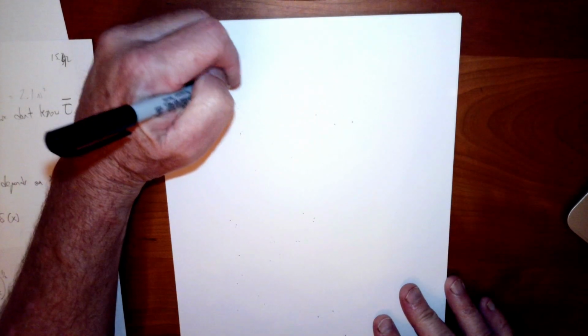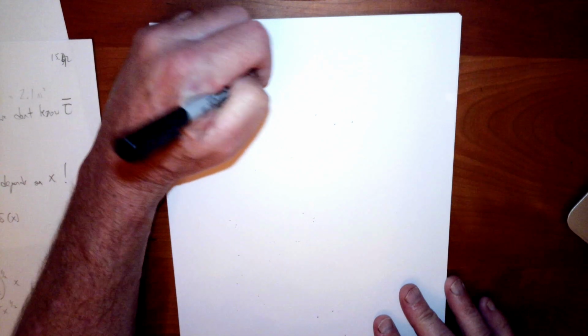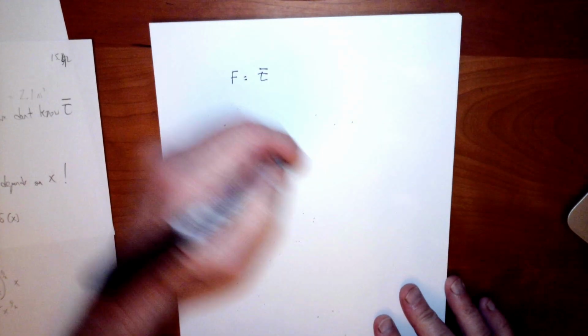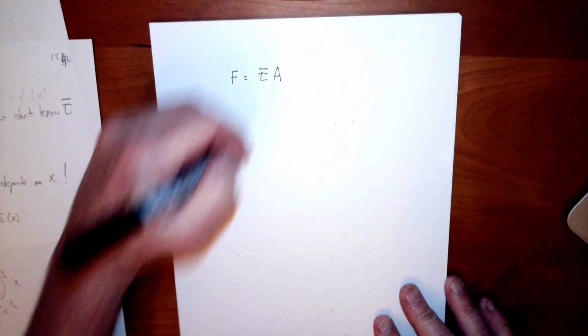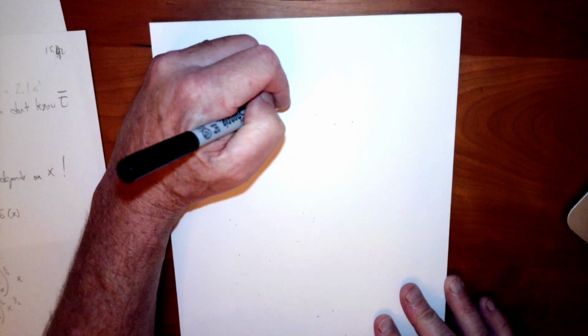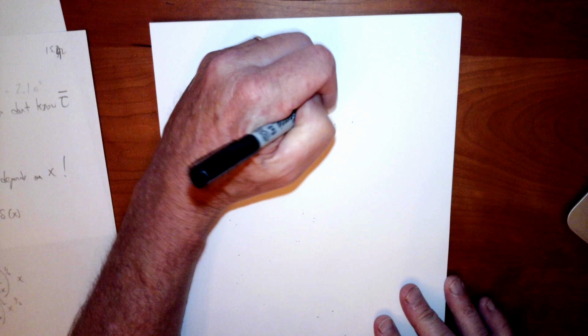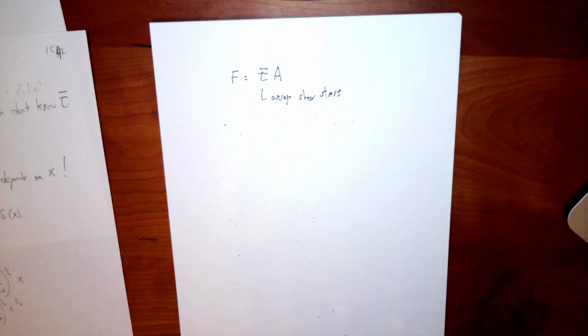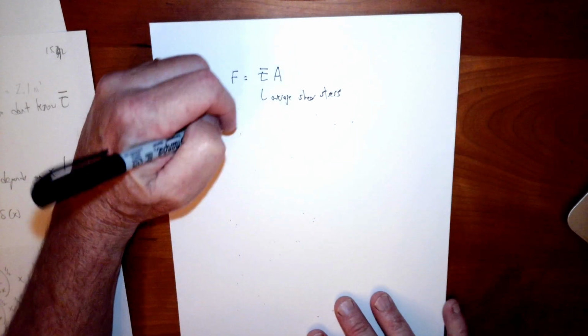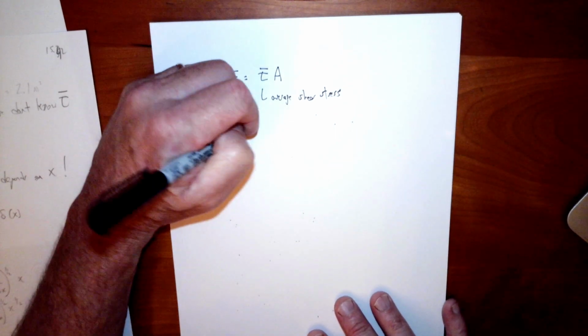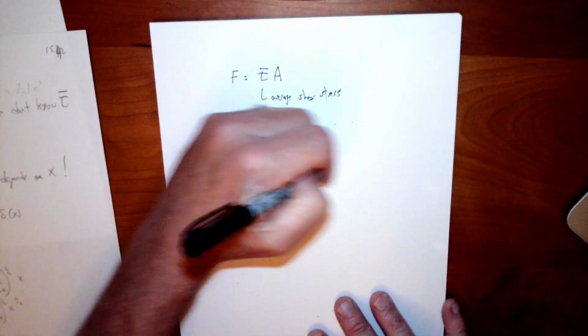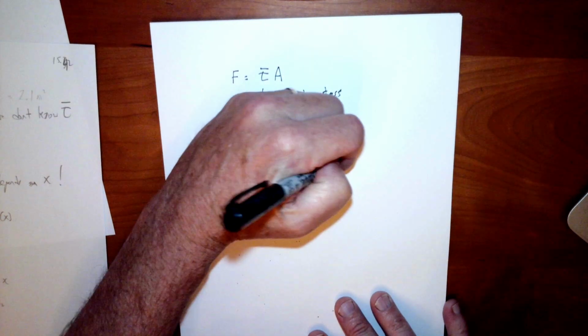So the force on the wing, or the total drag, would be the average shear stress times the total surface area, where this would be the average shear stress. But I don't know that. I know that the shear stress is a function of x. So the shear stress is definitely a function of x, because if you look at this delta, it's getting bigger, right?